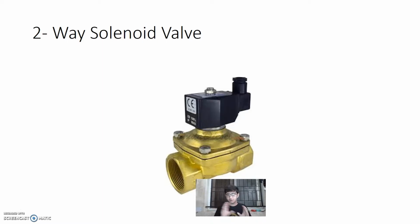That is called normally open and normally closed. When you are not giving any signal and your valve is allowing fluid to flow through it, it is called a normally open solenoid valve. And when you are not providing any signal, it is in its idle form, and the fluid can't pass through it, it is called normally closed.